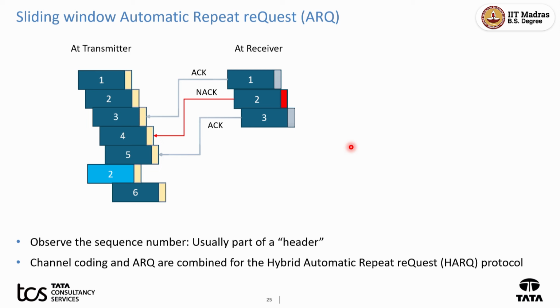But these are overheads. These are called overheads. You cannot avoid them. If you want to transmit 10,000 bits, you will have 100 bits of overhead. First, you have to send, I have space to transmit 10,000 bits. Straight away, that code block size was 6144. So, straight away 24 bits will go for that. Out of 10,000, I have got only 9776. Then I am adding some 10-bit sequence number or 16-bit sequence number. I have gone to 9760. Then I want to add some ACK information, another bit, it will become 9759. Then I want to make it a multiple of 8, it may become 9752 or 54 or whatever, right. So, these overheads will keep eating. Total capacity available includes all of this. So, we cannot escape it. So, it adds those sequence numbers and increases the overhead.